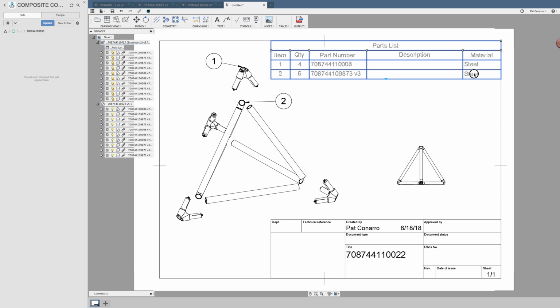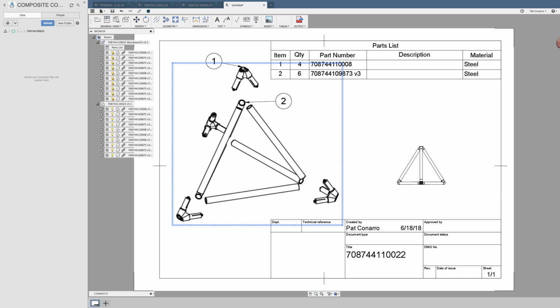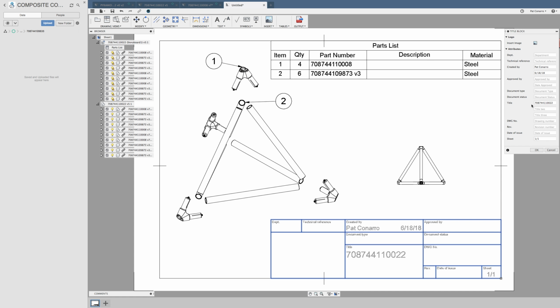The material needs to change to onyx, so you'll have to click on that. You'll have to change it in the properties of the part. And anyhow, so we're gonna grab this part number here, and we're going to save it as drawing number right there, and we'll say 150 10 millimeter pyramid.